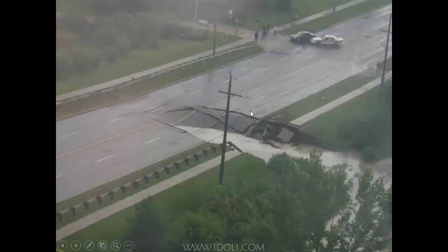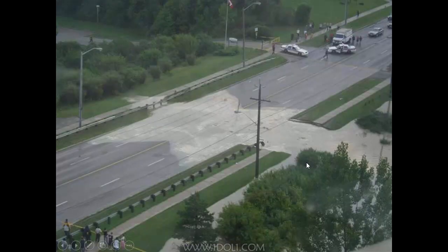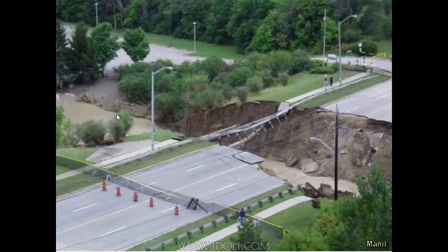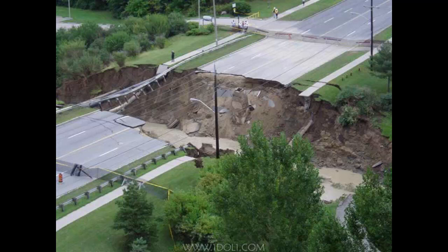So it just gradually was failing and washing away worse and worse until eventually you can see here in this photo that quite a lot of damage has been done, and this road's going to be closed for a long time because the headwater depth was getting too high and there was so much pressure that the seepage caused a failure of that foundation. Well, there's plenty of room for a proper culvert now, right?